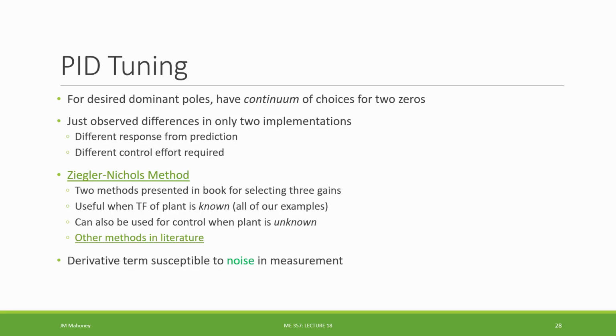So it's something to be aware of when we're using a derivative control as part of our controller scheme: how can we smooth it out, or how can we reduce the noise, or how can we limit extreme changes in the derivative control that's being exerted.